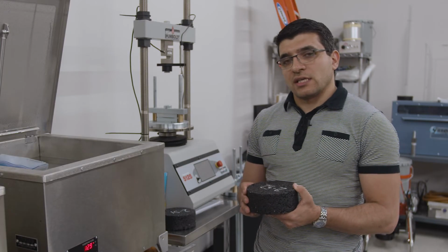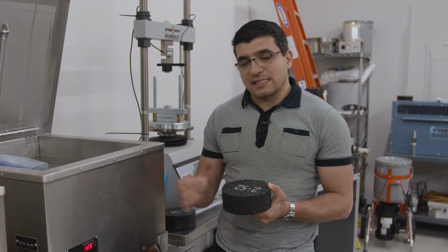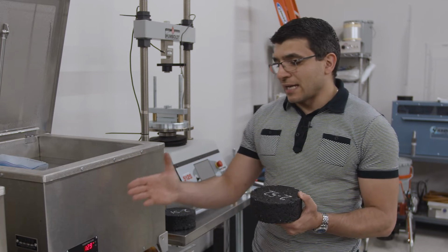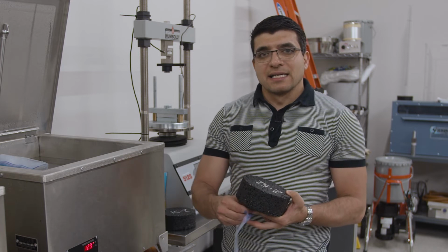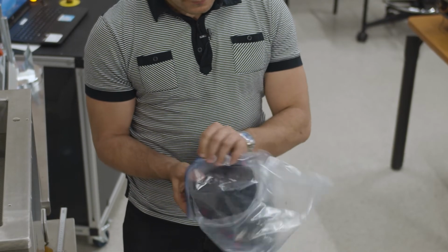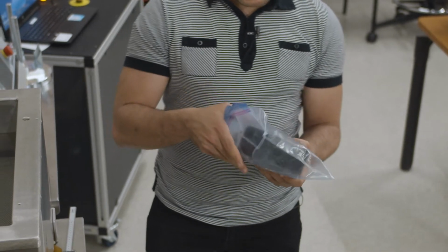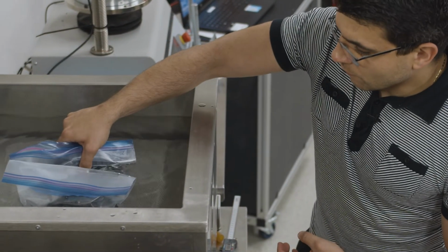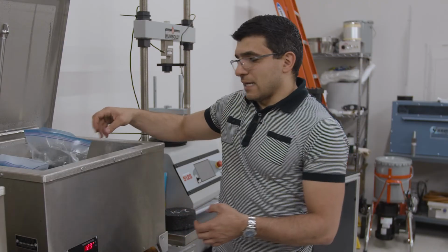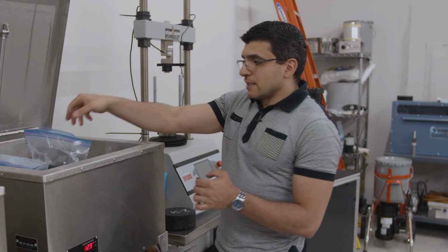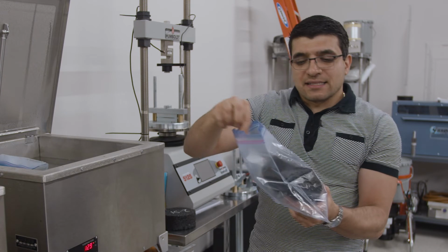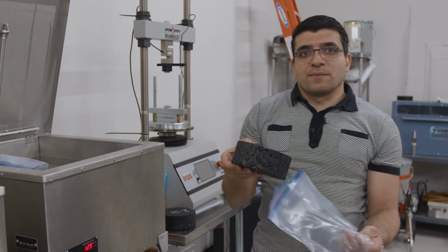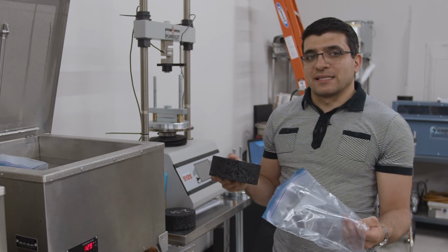The other way of conditioning is using a water bath. The water bath has to be previously conditioned or set at a temperature of 129.9 degrees Fahrenheit or 54.4 degrees C. We will be using a leak-proof plastic bag. The specimen will be placed into these bags. These bags have to be closed, and the specimen has to be placed into the water for a duration of 2 hours plus or minus 10 minutes. After that, the specimen will be taken out with the bags. We want to make sure that the specimen remains dry the entire conditioning time. The specimen will be taken immediately to the machine, and the performance test is conducted.